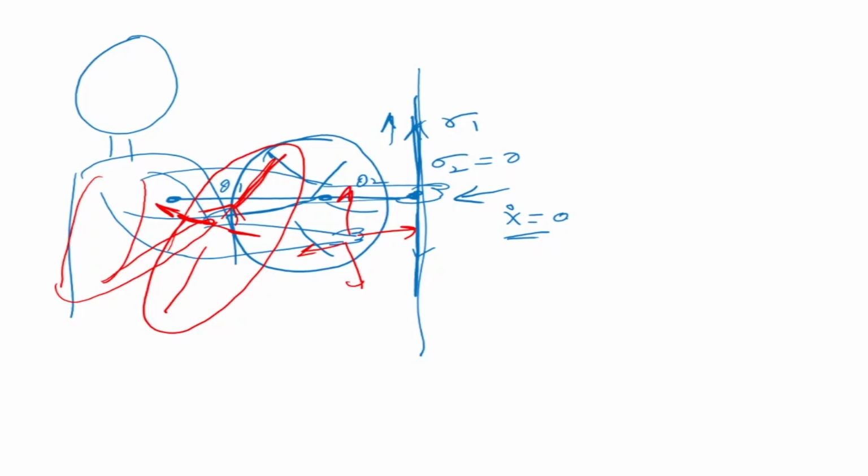So today we talked about the Jacobian, and the Jacobian gives us the relationship between the end effector velocity and the joint velocity. It also gives us an indicator of the energy. It tells us about singularity, and also about the manipulation ability, the direction in space where we can move easily and the direction in space where we cannot move easily.